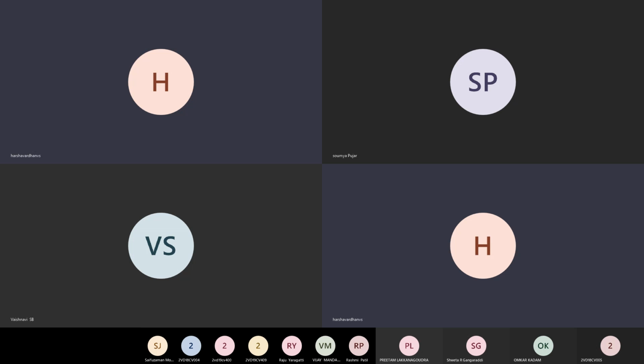The soil particles are disturbed. They are thrown out of the soil mass because the pore pressure is greater than the total pressure. The effective stress is 0.